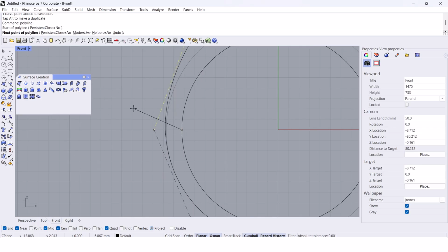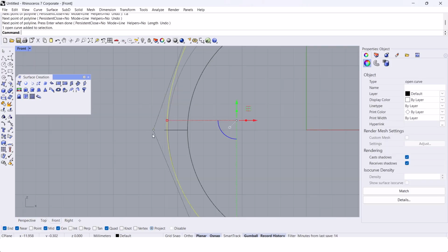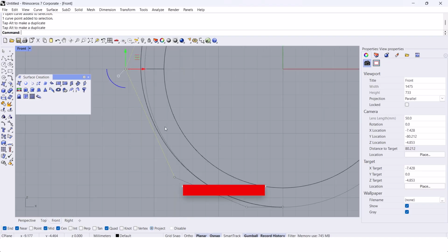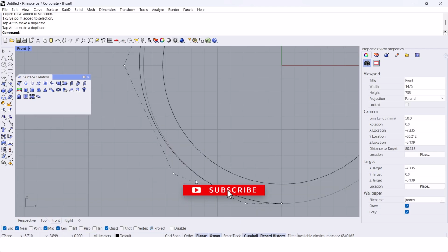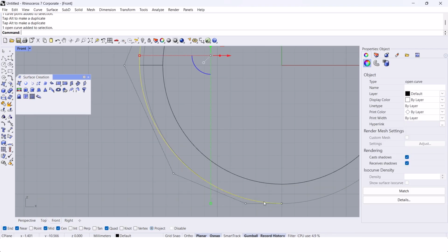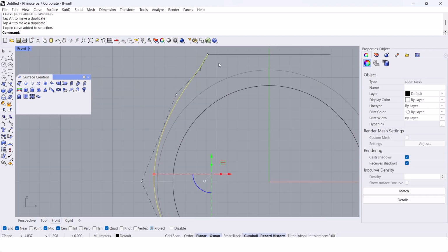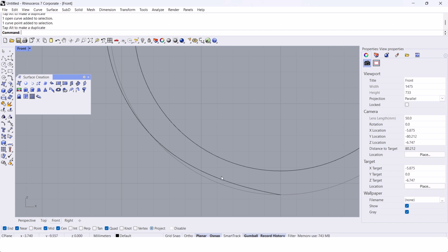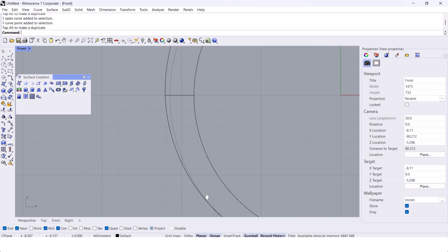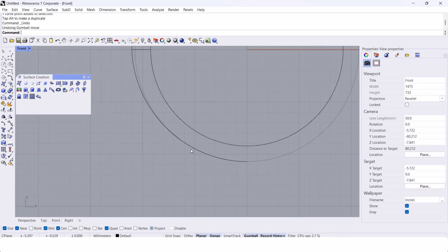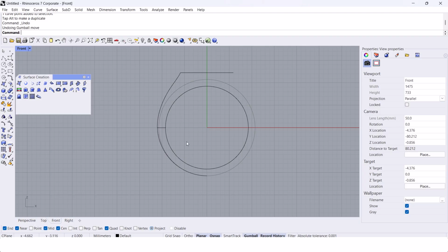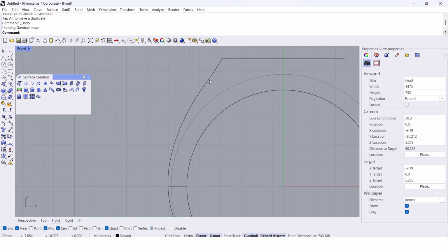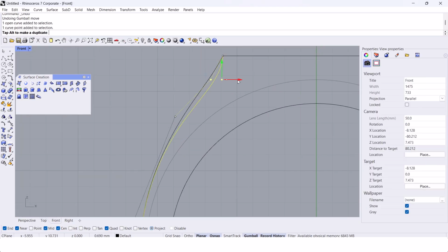Usually in my designs, I add, for example, 1.8 at this point, the side of the shank. I will manually try to manage it. Just take a look at the shape of the second curve here. You can see from 1.5, it starts increasing the thickness to the top. We don't like to have something like this. For example, it's 1.5 here, then 1.3, then again 1.5 and 1.8, and then increase. So this curve, which I put in the lock, is the guide to show us how smooth our surface is. I'm happy with the shape, but if you want, you can make different shapes.